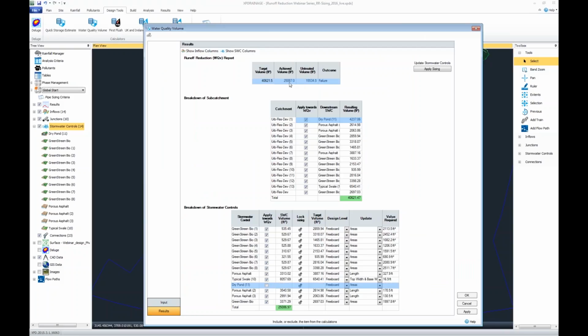So now you can see, well, we failed, right? Clearly, without the pond, we aren't storing enough. So we're going to need to upsize these facilities. Again, I mentioned we're going to need to upsize them 2 or 3 times their current size so you can really see a big difference. So I'm not assessing the pond. That catchment I also don't want to look at. So we can pick and choose what objects we size, what objects we include in this report.